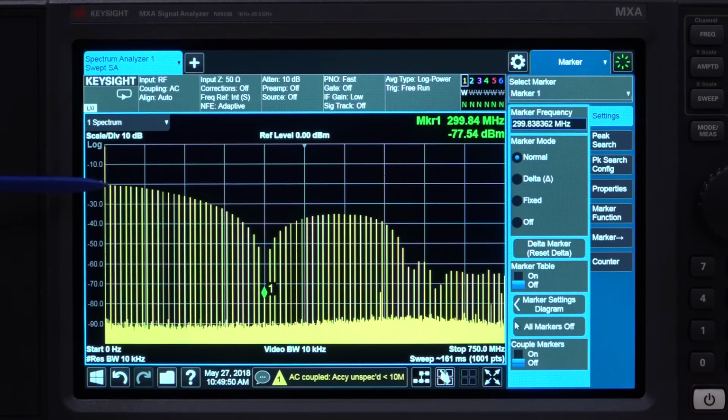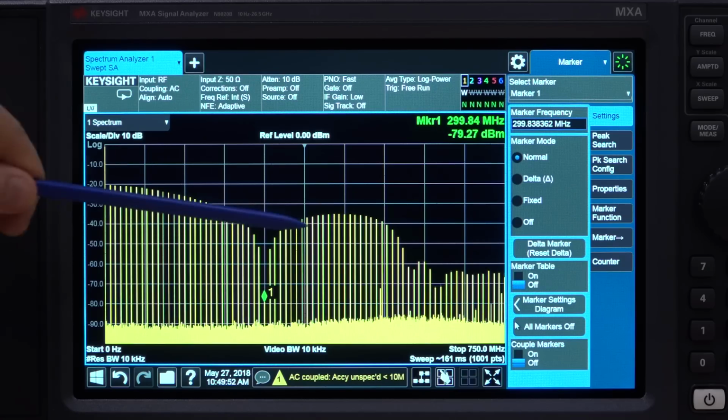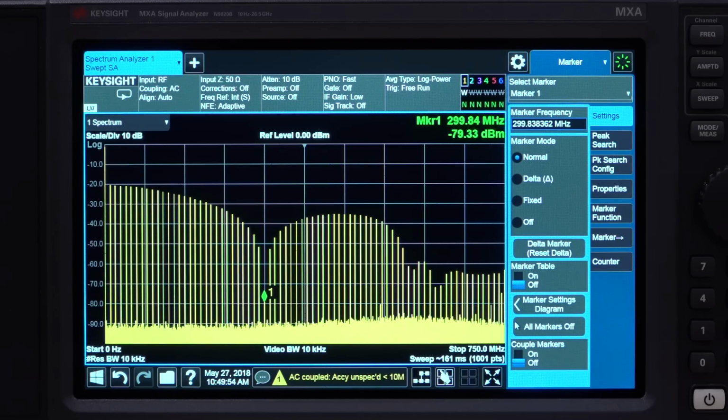But this is still fairly useful because we can use the shape here. If we were to record the shape and we know exactly the rate at which the signal falls, we can put a filter in front of this and then see the difference. That way we can measure our passives by putting impulses through them, essentially measuring them in broadband. And you would still need a spectrum analyzer, of course, to do the measurement, but nonetheless, it is possible.